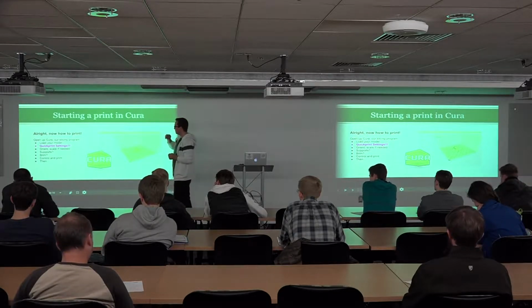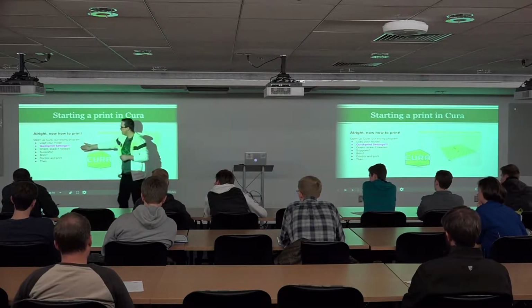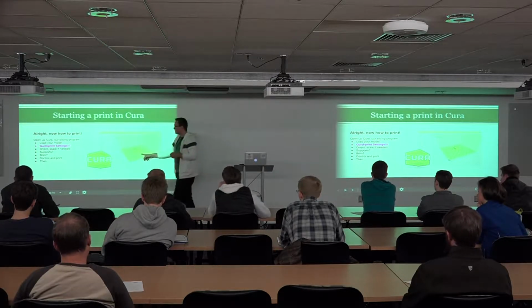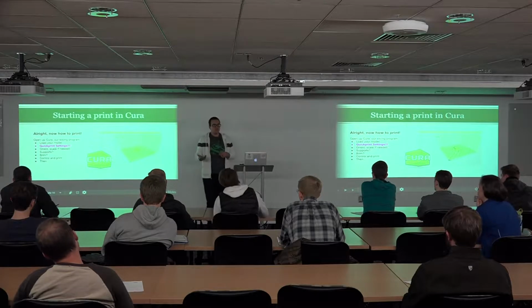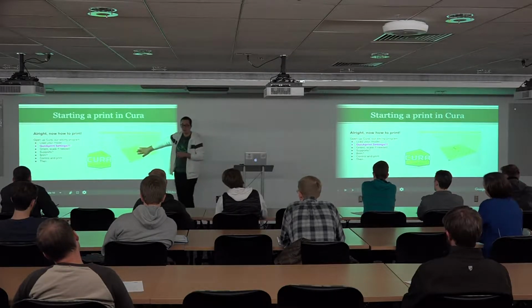And then, oh yeah, orient and scale if needed. That's the other thing about STLs, is they don't have any units. So if you designed them in millimeters, it'll show up at the right size.